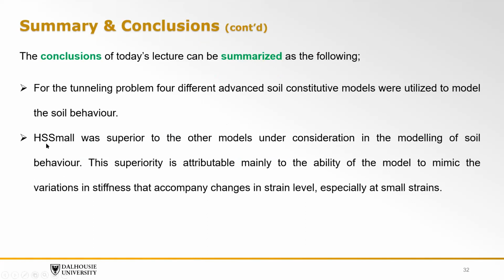However, the hardening soil model with small strain was superior to the other models in modeling the soil behavior. This superiority is attributed mainly to the ability of the model to mimic the variation in stiffness that accompanies changes in the strain level, especially at small strain levels, which is very important in tunneling problems.